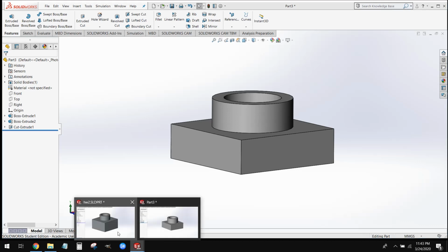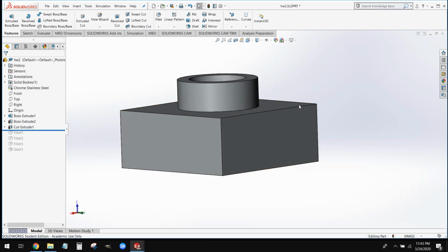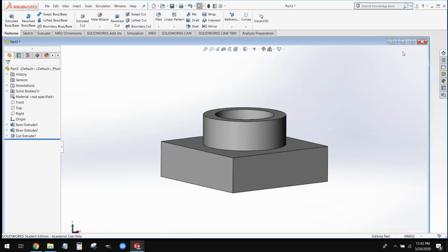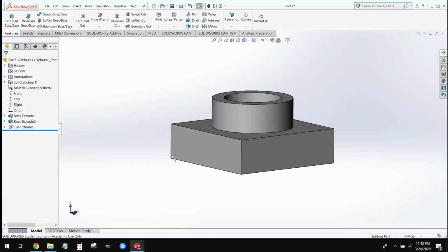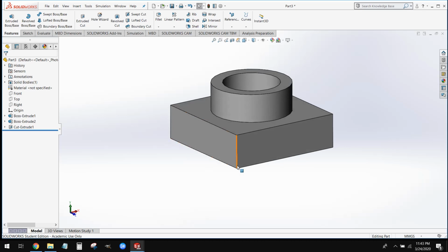Now, when we look back at our finished model, you might be able to tell that the dimensions of this model are slightly larger. What we're going to do is update our model to reflect those slightly larger dimensions. Instead of 100 by 100 for the footprint of this box, we're going to grow that to 120 by 120. And then instead of 30 millimeters for the height of this box, we're going to grow that to 50.